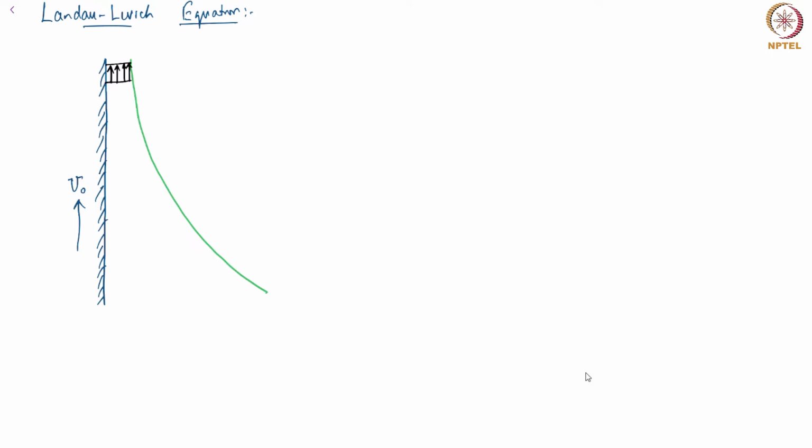Why would the velocity be uniform? Because you have no slip on the wall. Therefore, the velocity should be u0 on the wall. But at the same time, once the interface becomes vertical, meaning parallel to the plate, the tangential stress is also zero, which would mean the velocity profile is flat.